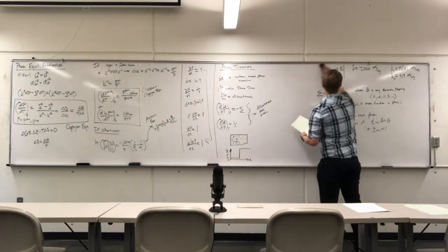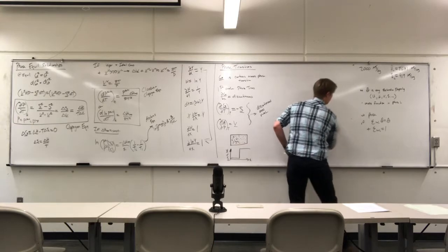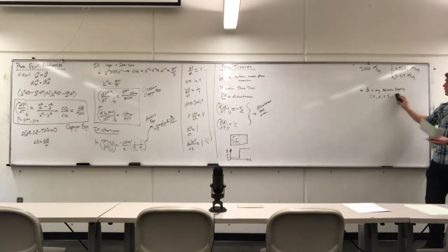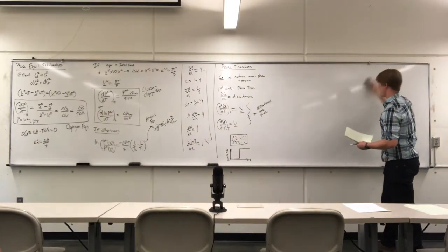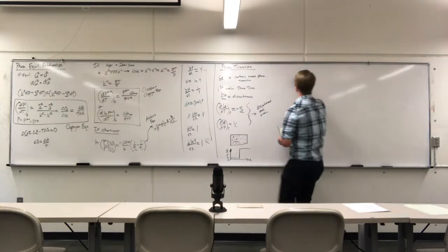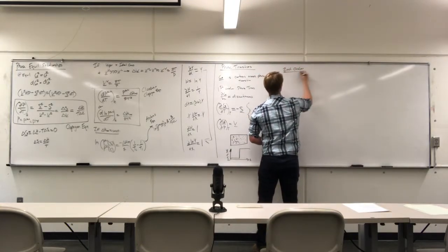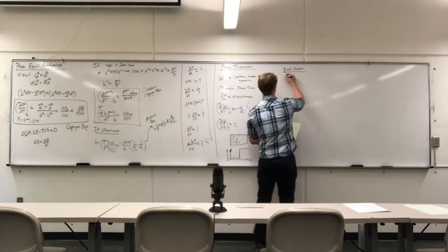They also have second order phase transitions. And this is something that as chemical engineers we will very infrequently see, but as material scientists or metallurgical engineers, that can be seen. The second order phase transition is where the second derivative of the Gibbs free energy is discontinuous.